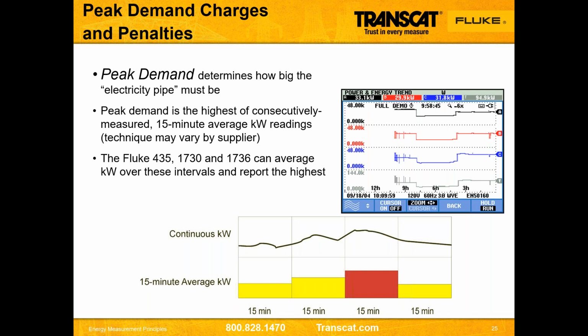So we can figure out what's using that large scale amount of power and possibly put it on another device like a soft start or a VFD, variable frequency drive, to reduce that inrush current that actually is driving up the peak demand. And these are all things I'm mentioning that a power analyzer can configure and measure, so you can figure out who is using all this energy.